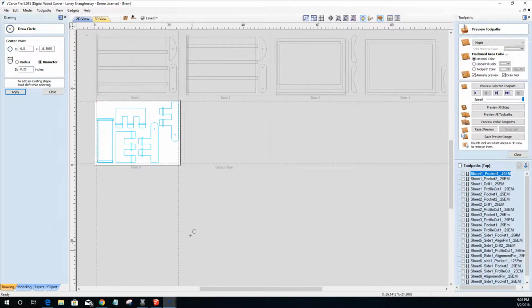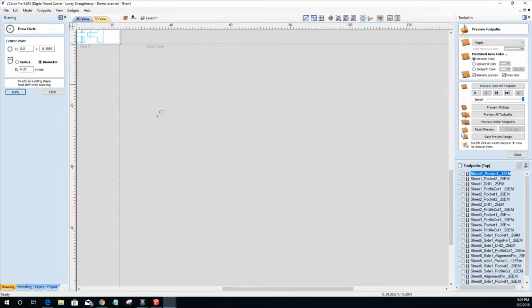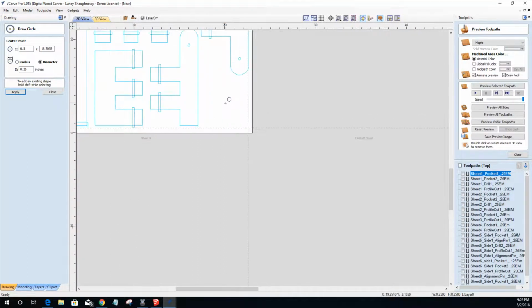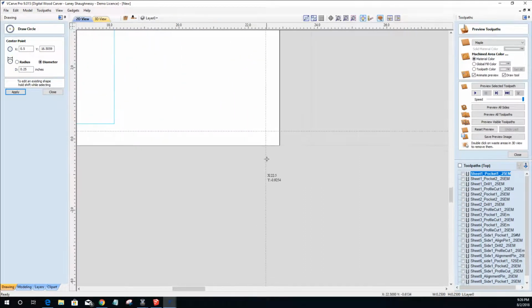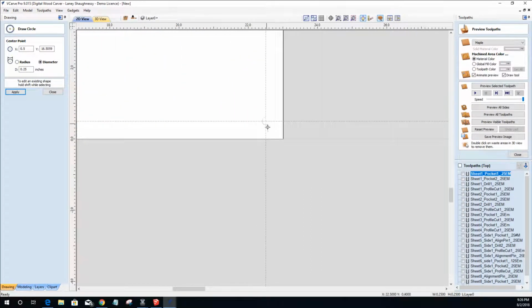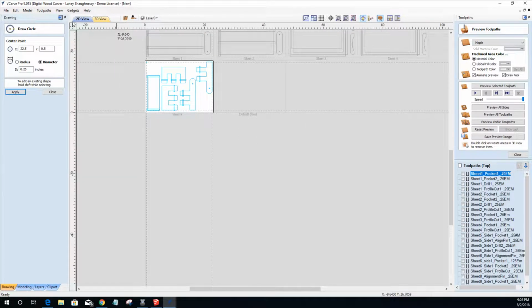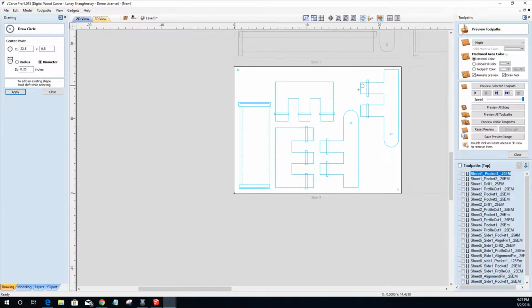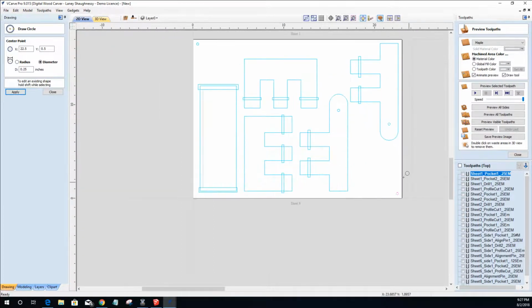It's rinse and repeat, and that's the process of how you would look at and go through your Vectric files if you're bringing files in from SketchUp. Let's go ahead and make this 0.25. Okay, turn my guidelines back off. And let's go ahead and make the toolpath.